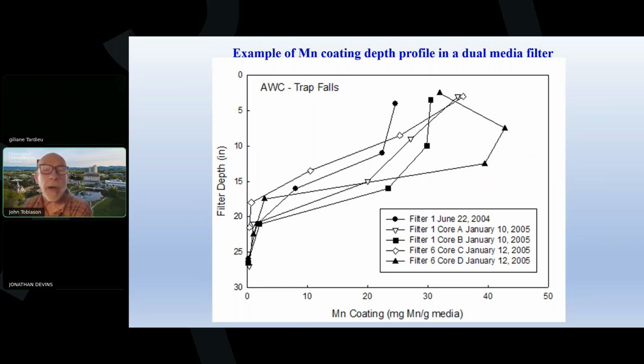So it makes particles. And those particles that are created from permanganate, not from the original manganese, need to be removed. And they sometimes are electrically stable. They're best removed if that's done before coagulant addition. But other times, if there's precipitating iron, they can be effectively removed as a particle removal. So that's what I mean by that. All right. So permanganate, you can't have it existing in water you deliver to consumers. It makes pink water, and then it precipitates as manganese oxide.